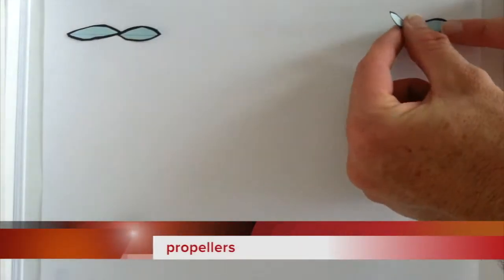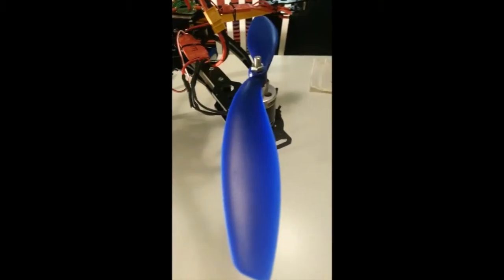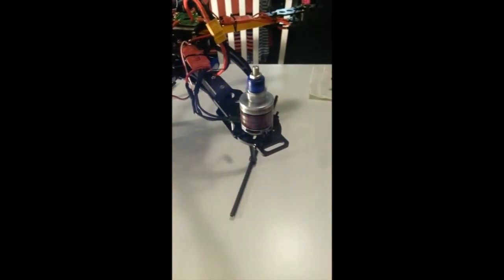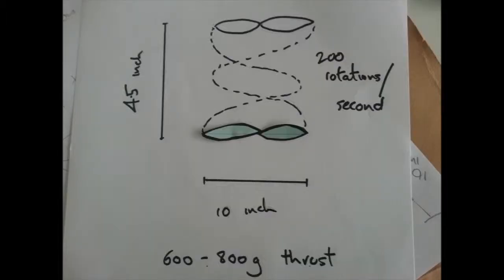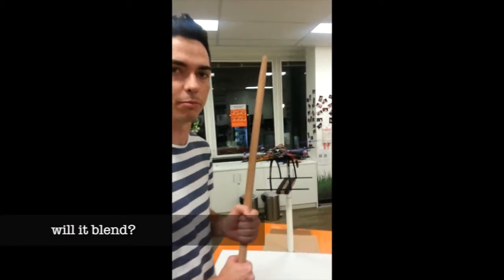To generate lift, we need propellers. The propellers we've chosen are 10 inches long and cause a displacement of 4.5 inches for every complete rotation they make. Given they'll be making 200 complete rotations per second, roughly, we expect this to generate about 600 to 800 grams of thrust, which, given we have 4 propellers, should be enough to lift our 1.5 kilo-ish quadcopter with a small payload. Quadcopter test. What happens when we stop the propeller?